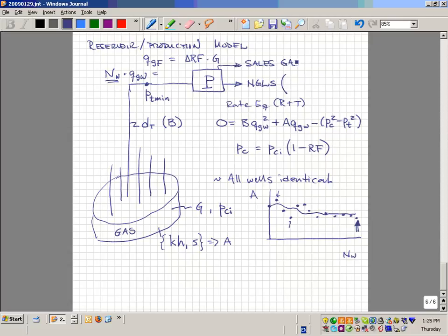And so the processing is going to be more or less efficient depending on the temperature of what we'll call the dew point controller. That will be the main process variable. An assumption is being made that the incoming stream composition, that it's a wet gas reservoir, meaning that the composition of the gas is invariant or constant with time. Okay? So the flowing well stream composition is assumed to be invariant.